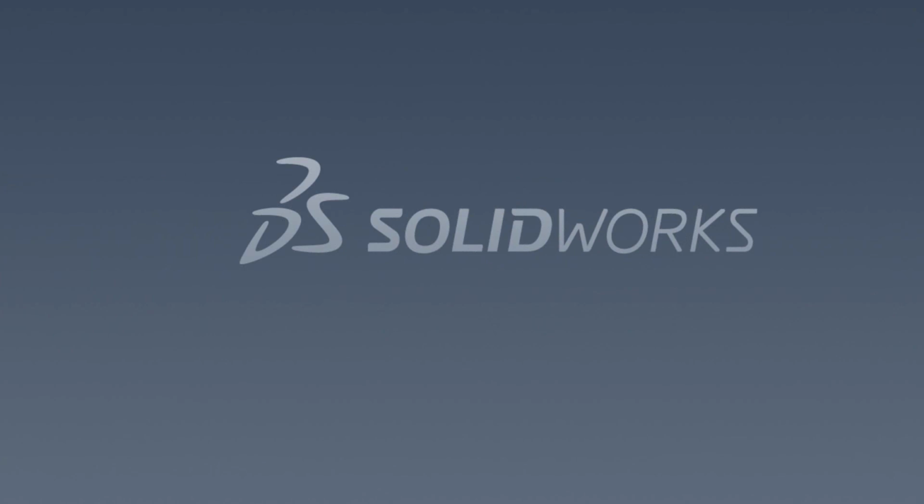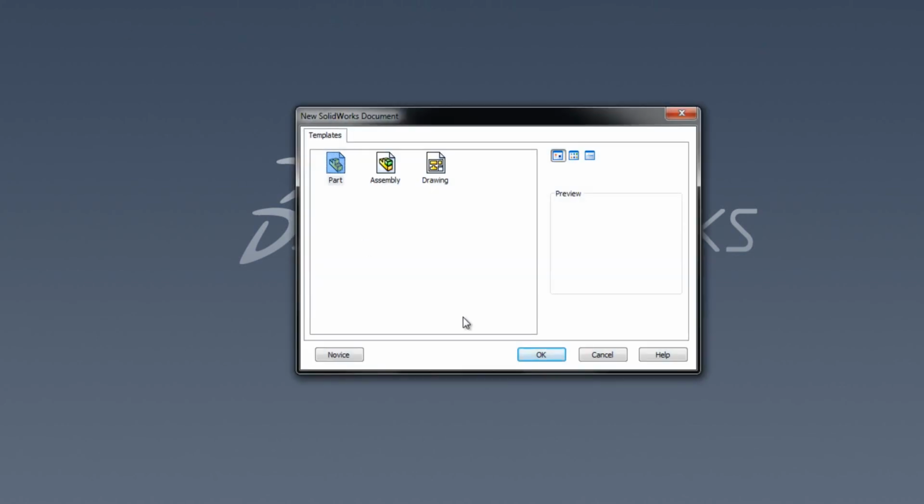Within SolidWorks, we can just start up a new document. We want to start constructing the first of our templates. The first one I'm going to start working with is a part template. So I'm just going to go to File and New, and we can start from any blank document. When users normally go to File and New, they'll find a menu like this one, where you've got either a novice or an advanced screen, and we can just select the part from there to open up a blank document. This brings in a series of properties and settings that we can adjust.